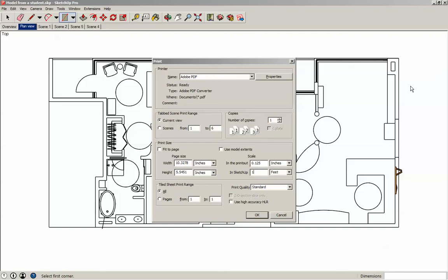As I mentioned, SketchUp will print whatever it sees on the screen, so it's probably printing some white area on either side of this. I could get rid of that if I wanted. But anyway, then you just click OK, save your PDF file, and you can walk over to the Digital Print Lab, and it will preserve the page size, the page setup, and any styles that you've applied. And that's basically all it takes to print from SketchUp.